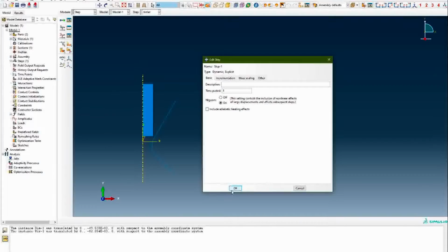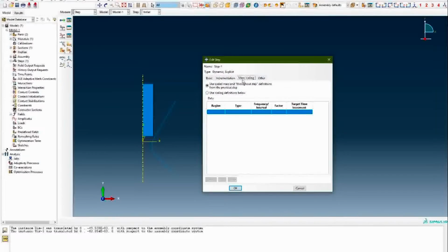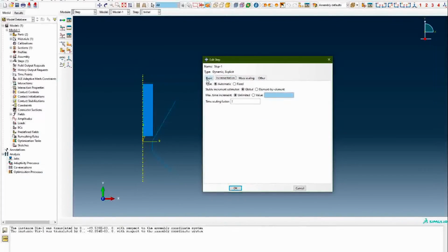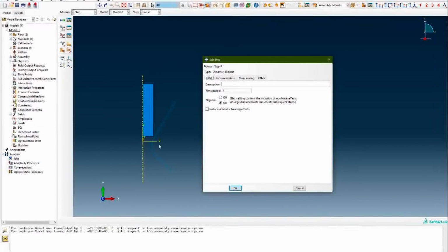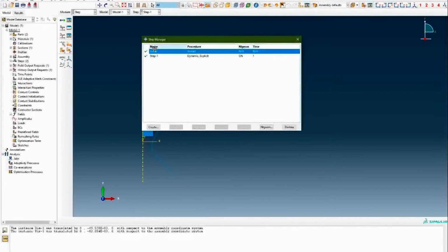So just leave these other three sections here. I will explain them in other videos, but this video is only for very beginner students who just want to know how Abaqus works. So consider the time period as 1 and click on OK. So you can see one step is created.